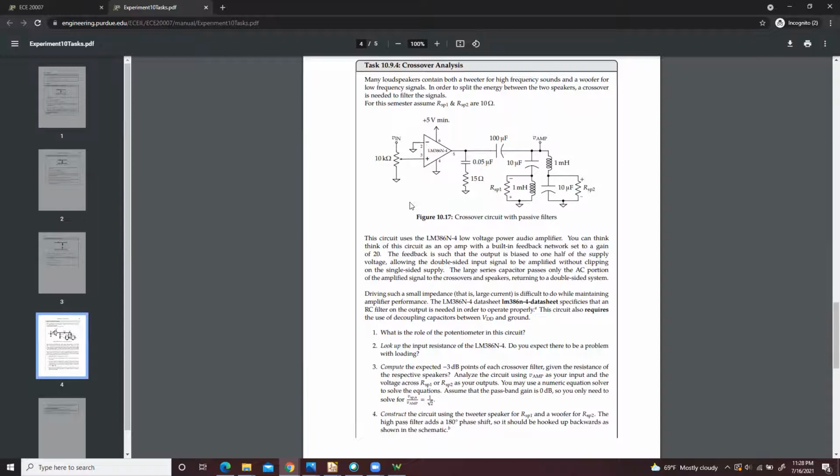And when you apply a 516 ohm resistor at your output, you would see the output voltage change. Okay, so the ideal voltage should be 2.5 volts for that task, right? But when you put the 516 ohm resistor, the value decreased. That's because of the loading issue. So you want to think about that question and relate this circuit to that question and answer it.